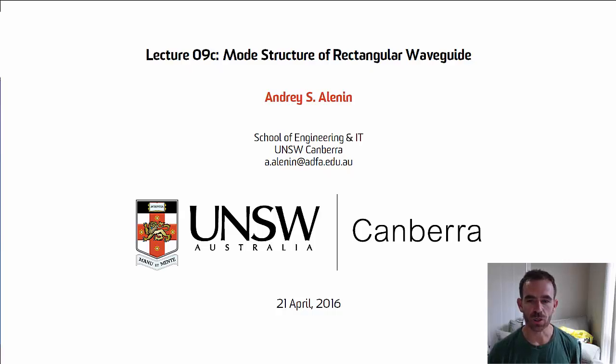In today's lecture, we're going to look at the mode structure of the rectangular waveguide. In the previous two lectures, in lecture 9a, we developed the expressions that allow us to compute E sub x, E sub y, H sub x, and H sub y, the transverse components of the E and H fields, in terms of the longitudinal components, E sub z and H sub z. And in lecture 9, we then did separation of variables on those longitudinal components in order to define the TE